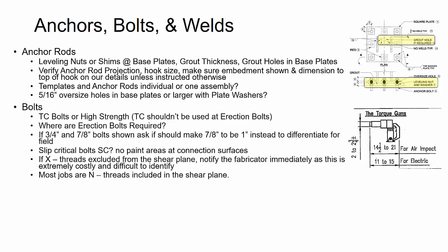Oftentimes you'll hear fabricators and erectors say that we want to use TC bolts, or tension control bolts, everywhere. So TC bolts are great. They will fully torque the bolt, but the advantage of them for the fabricator and erector is that they can much more quickly erect the job. They can get the bolts in, tighten them up, and they can move on. And so if they can at all possible, many of them will use TC bolts.